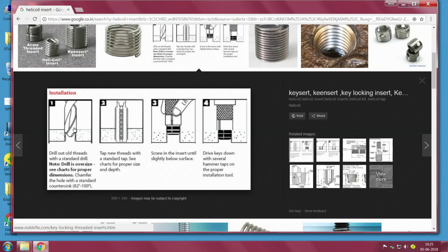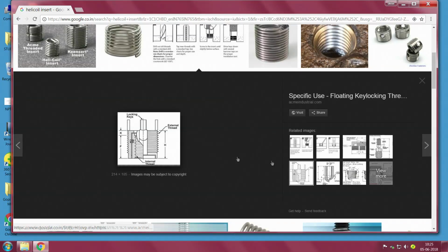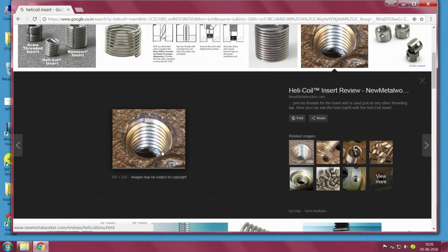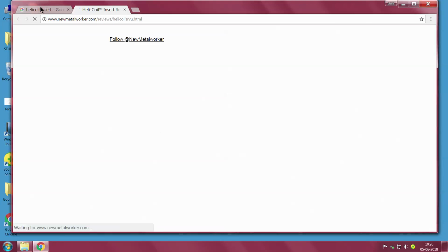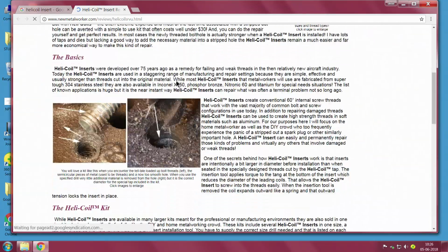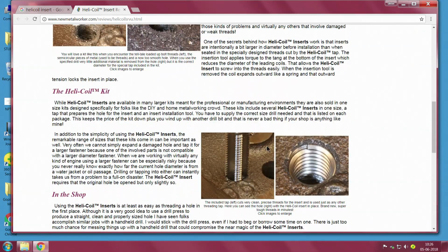This is typically the way this helicoil works. You have a hole, then you have a special tool, then you have a device which inserts it for proper installation and so on. So, this is standard practice when it comes to making these things. There is a good view about it here. Of course, often it is used more as a repair, but the reality is more than repair, it makes sense when we actually insert it like this. You see this?